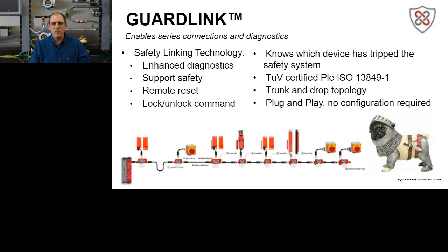And I can just remember being in my jacket, my hands cold, trying to find out why it didn't start. And saying, okay, something has triggered the safety. Because you've got flying knives in this machine, you have to actually latch these doors shut. And once you latch them, it doesn't necessarily mean the sensor senses that the door was shut. So we had to have somebody go around banging on the guards, trying to find out which guard wasn't latched properly. Find out which one it was, unlatch it, adjust the sensor till you get it right, and then lock it back up and start running. That was just so frustrating.